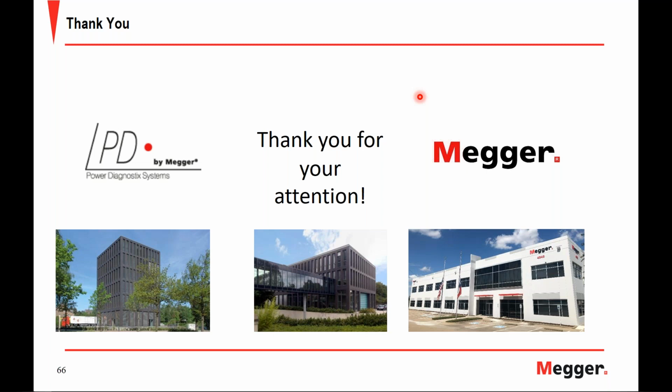But my first recommendation is that a fairly good compromise with every new motor is, first of all, you need to have the factory acceptance measurements for PD and tan delta during the production stage, which is basically your reference value for the future. And what you can do is, from the very beginning, install capacitive couplers in the terminal box, which allows you to connect online. And if you start to see something in the consecutive offline measurement during the next major turnaround, or you see an increasing trend or a developing PD pattern during periodical online measurements using these coupling capacitors, then the next step could be to decide for continuous monitoring.